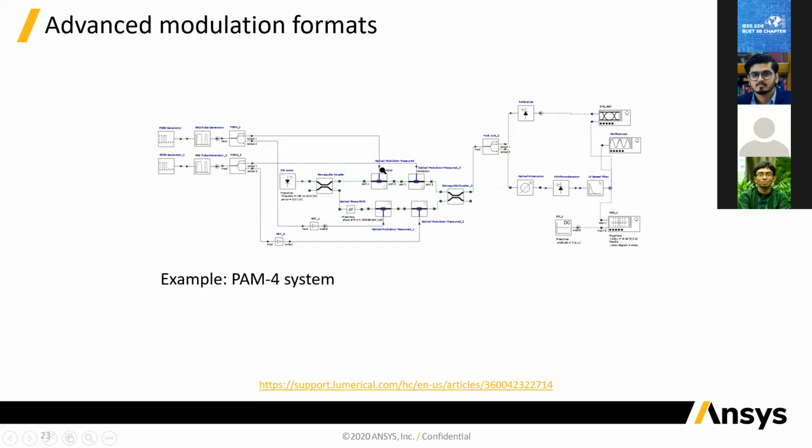And that way you can modulate multiple bits together in the same circuit. So here you have two modulators in series, or two phase shifters in series. One takes in the most significant bit, and the other one the least significant bit. So your information can be 0 0, 0 1, 1 0, or 1 1. Based on that, you incur different amounts of phase shift in these two arms. And so the output that you get can have, say, 4 different amplitudes for the 4 different bit sequences.